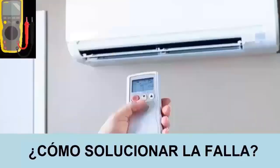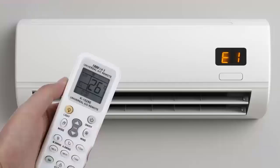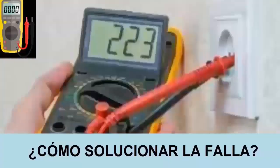Steps to diagnose and resolve the error. A. System reset. Turn off the inverter unit, cut the power supply, and wait several minutes before restarting it. B. Check whether the mains voltage is stable. To do this, use a multimeter on the AC voltage setting.